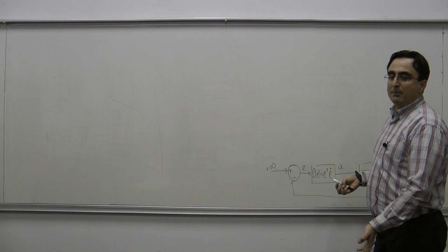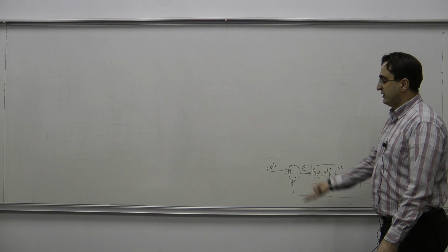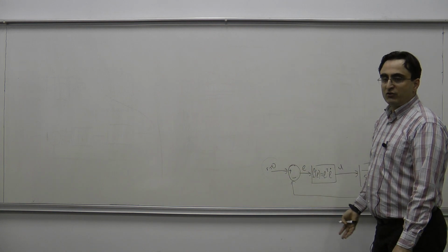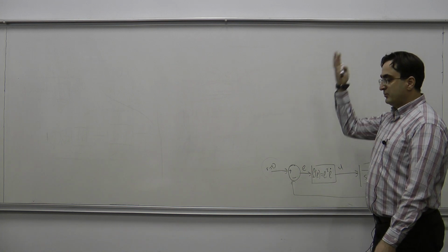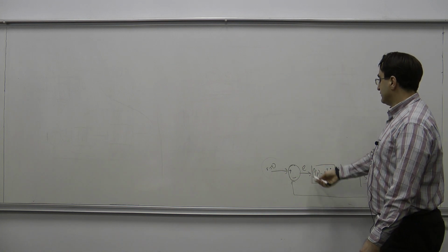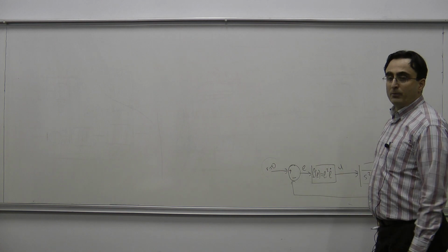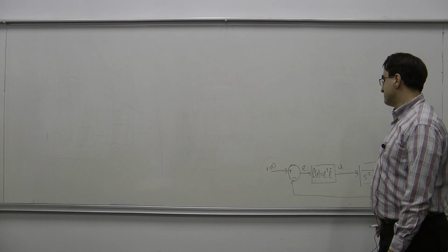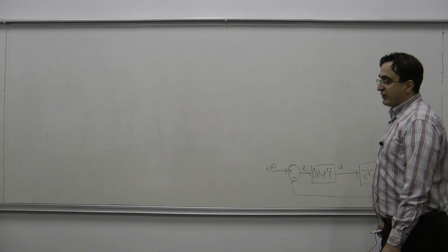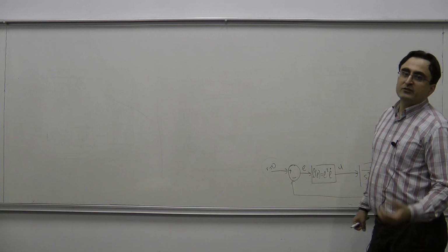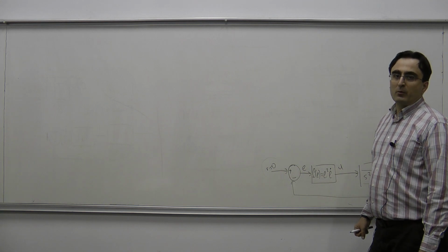What is going to happen to oscillation? This E is going to change with some magnitude, and the usual linearization might be useless with that large operating range. Okay? So here, describing function analysis makes this linearization in frequency domain.